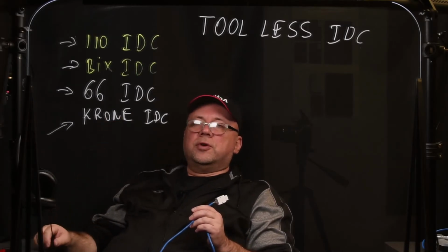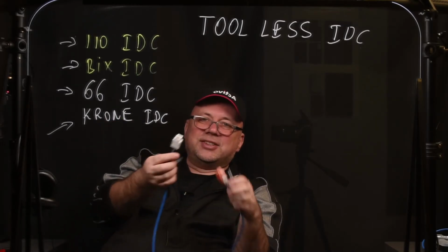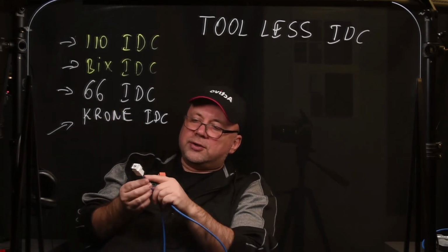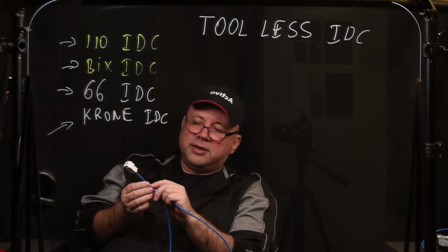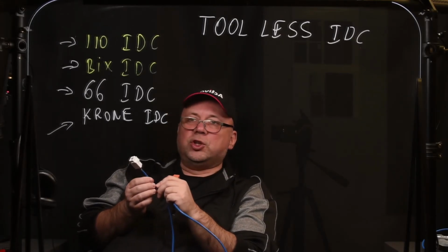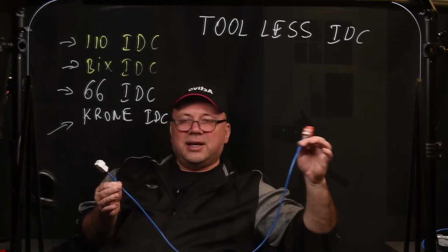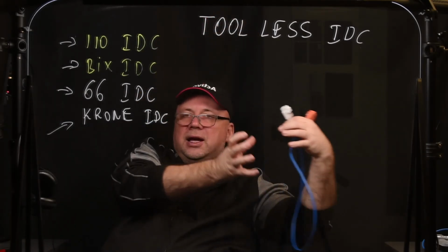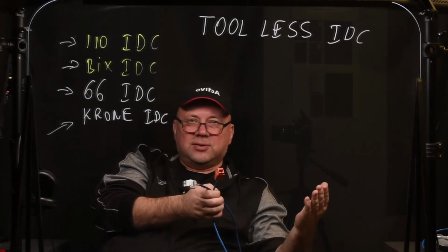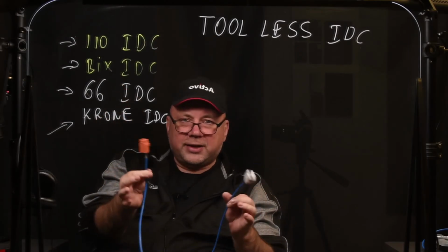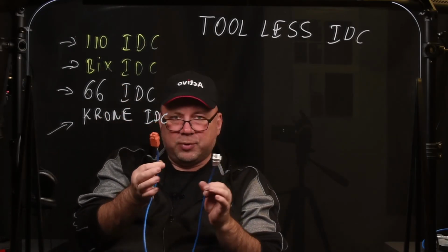Now, it is very important to have those labels the same at both ends. If you go to the wall location and say, okay, this is data jack D07 or D08 or D72, then at the other end you're going to have a bunch of cables coming out of the ceiling at the rack location, and you have to make sense of that. So all the labels have to be kept. So I'm going to get you to practice labeling cable at both ends.